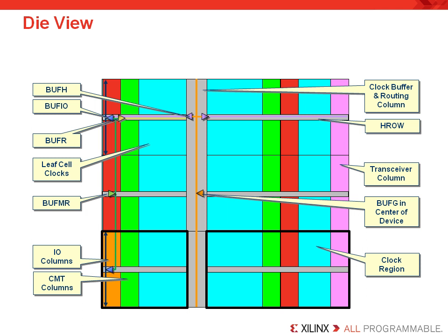Each device has 2 I/O columns, one on the left edge and one on the right edge of the die. You should also note that the I/O pins associated with each clock region are placed in a single bank associated only with that clock region. There are also a number of BUFMRs that are dedicated buffers that allow clock inputs to drive the BUFIOs as well as the BUFRs of adjacent clock regions.